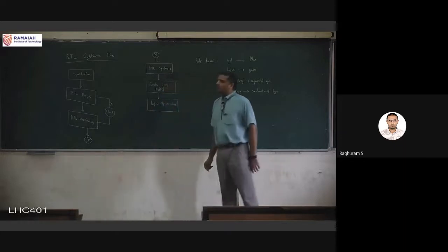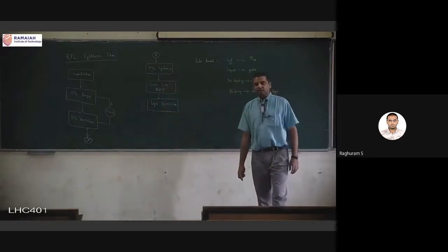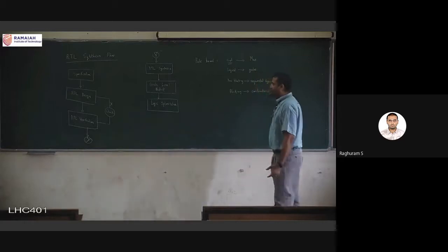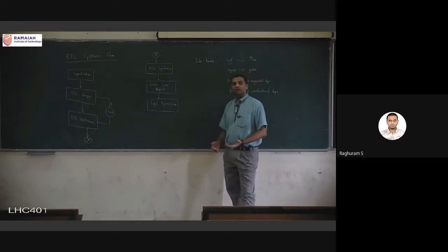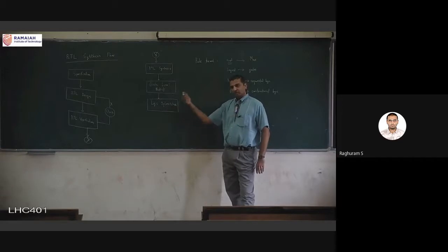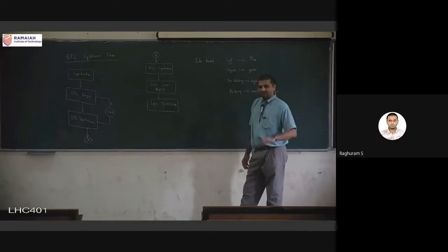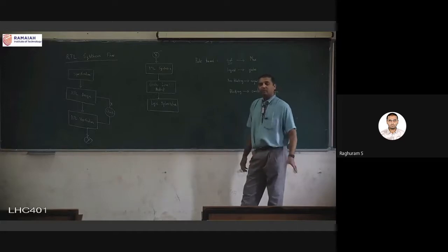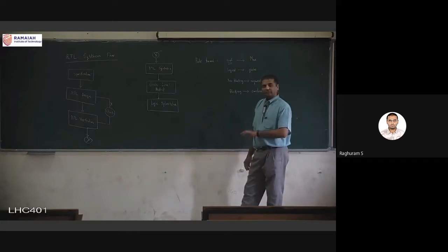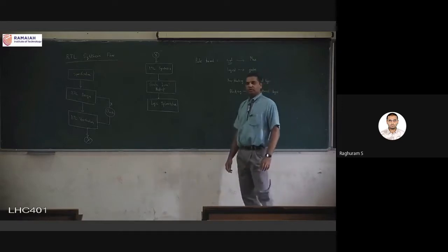one very important step is called logic optimization, and you have already done this if you have ever used the K-map to simplify a logic expression. That is an example of logic optimization. There are many more higher levels of logic optimization also. One level higher than K-map, if you have for example 5 terms in the expression, there is something called the Quine-McCluskey method, and there are other commercial logic optimization tools also. Many of them are open source. If you search, you will find them.